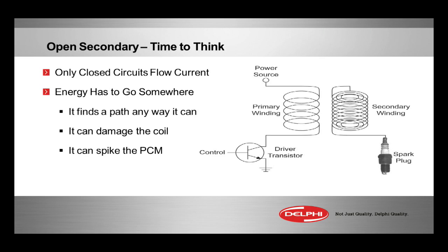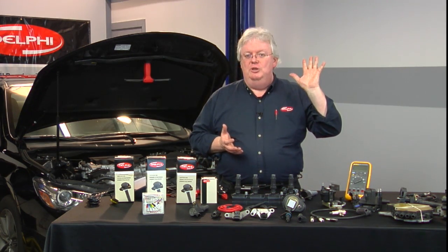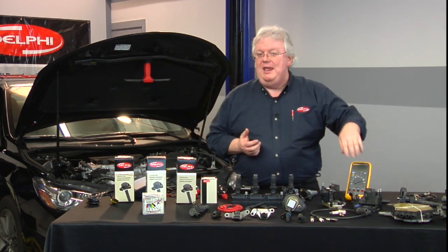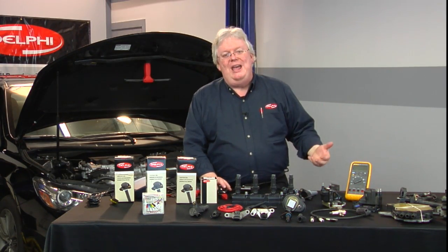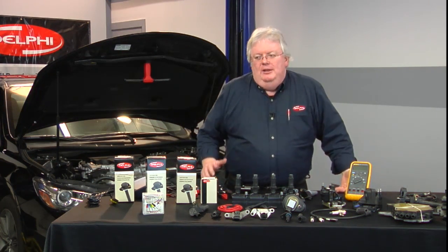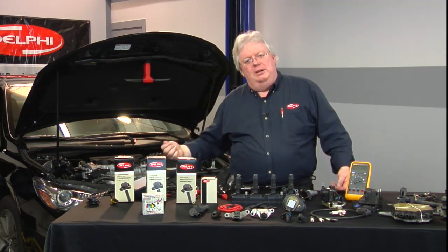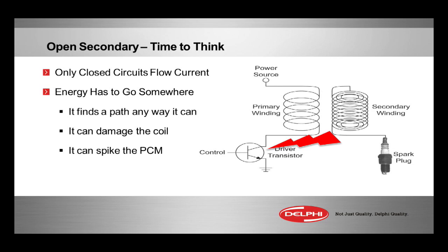Spiking can cause module failure. They don't like that. They don't like excessive heat, and they don't like excessive vibrations. They don't like to be dropped either. So if that happens, you might not want to trust that coil. You might want to get another new one out of the box because it may fail either immediately or soon after you put it in the car. So it's like any other module. You wouldn't drop a PCM 3 or 4 feet to the ground, pick it up and throw it in the car. Same thing here.